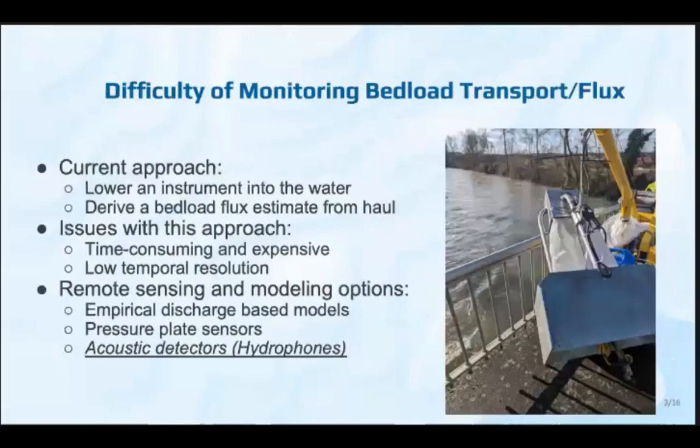Unfortunately, tracking bedload transport, the state of the art to get a direct measurement, is to drop a net into the river and count the number of rocks that you collect and do a grain size distribution at a lab. That process is pretty expensive. You have to send like 3 or 4 people out there, and it's time consuming, and you get a pretty low temporal resolution. You can only do this maybe once or twice a season. So the need for a remote sensor is pretty important.